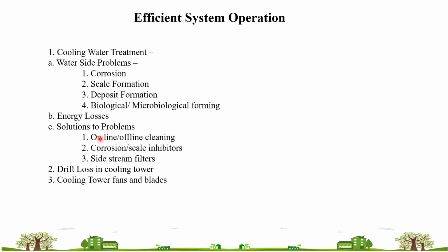After 28 degrees Celsius, if your basin temperature is 28 degrees Celsius and you are not operating the fan, there is a chance the temperature will rise. So the design of that particular feedback has to be very strong. So you can use that methodology of a proper feedback based system. Right. With the feedback system, we can use. Yes, we have to ensure that there should not be any compromise on the process.